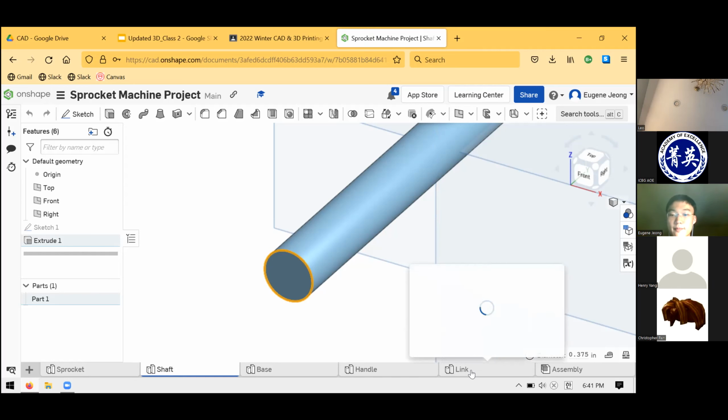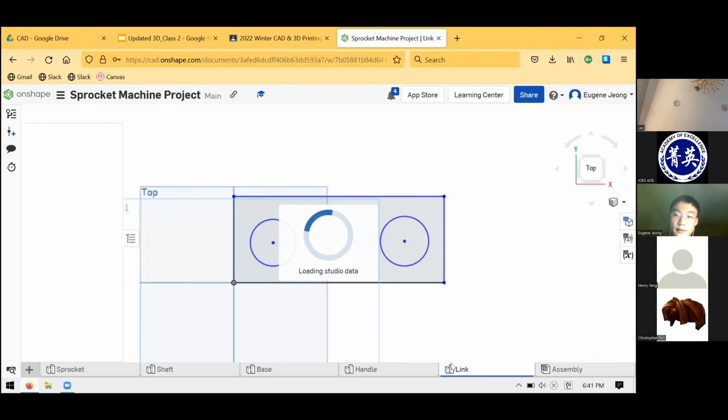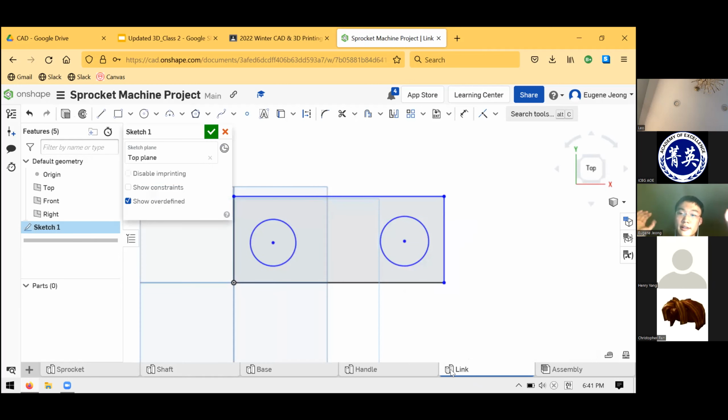So if it's 2, you can just make it 2 and they'll line up with each other. If you make it 2.1 in the model, you'll get a tiny gap of about 0.05 centimeters radially. When it comes to real life, though, when you're actually manufacturing things, especially 3D printing, that is something you really have to think about, because in real life you don't have exact perfect numbers. Everything is always going to have a plus or minus tolerance on it.